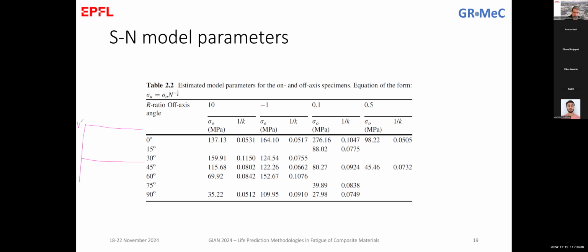So this is a creep test. You go to a sigma max, and you stay there. And this is exactly the definition of R equal to 1. So in this sense, the creep testing can be considered as a subcategory, if you like, of fatigue testing at a specific ratio.